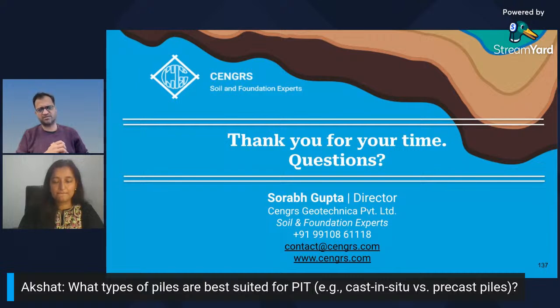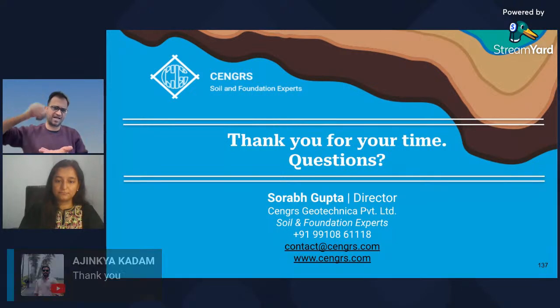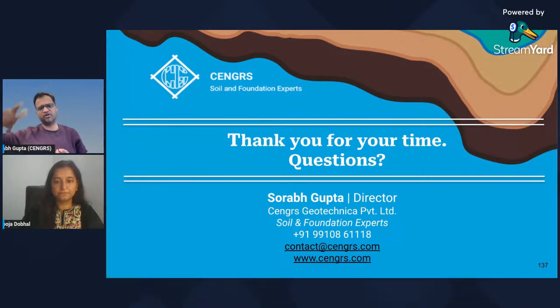Naturally, if you have precast piles, the possibility of changes in cross section is almost nil because it's a precast pile. So in a precast pile, PIT might be done to figure out if there is damage at any particular depth. The only fear with a precast driven pile is that sometimes, when you're driving the pile, you end up breaking it at certain depths. If you haven't caught that during the driving process, then PIT could be used to figure out the depth of the defect or the crack.